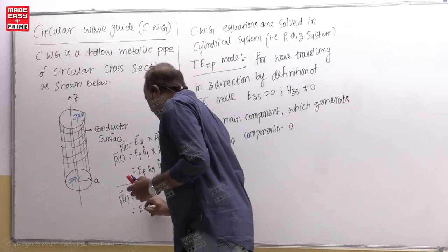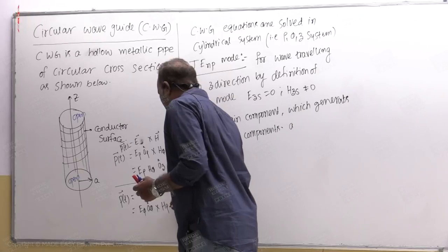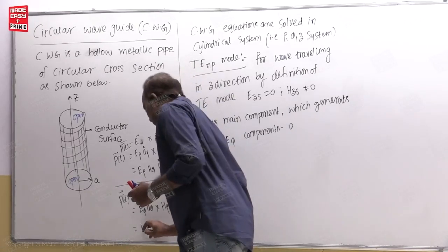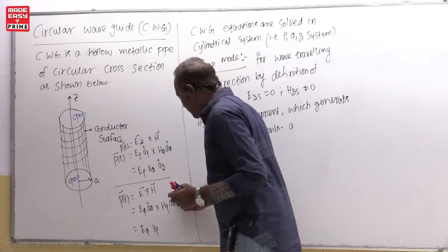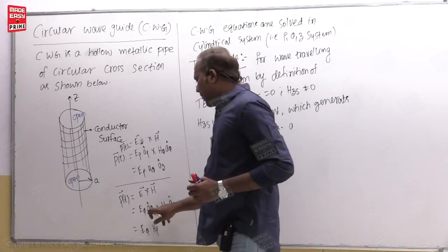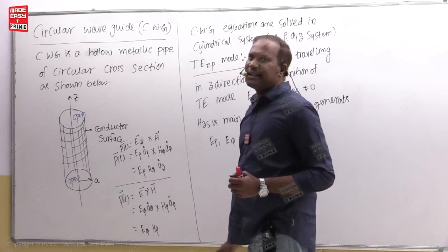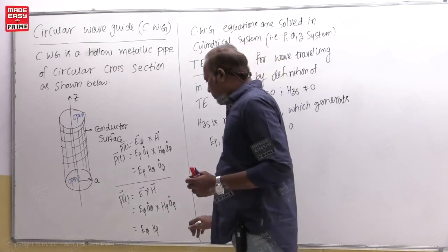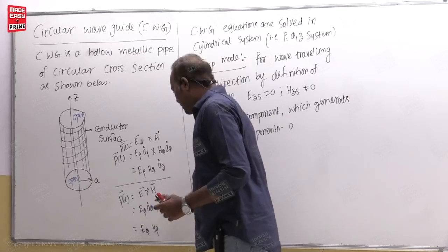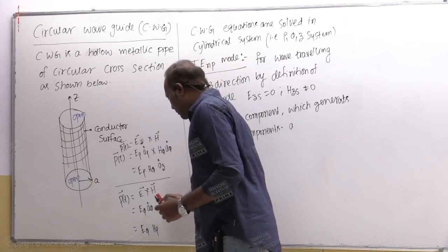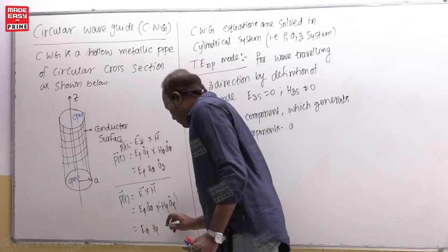Then the electric field phi component cross the magnetic field rho component. So here E rho, E phi, H rho. The electric field phi component generates the magnetic field rho component. A phi cross A rho becomes minus Az, right? Minus Az. Then one of them will have opposite sign. So ultimately, for example, for this you take minus, and you will have once again this one as Az.